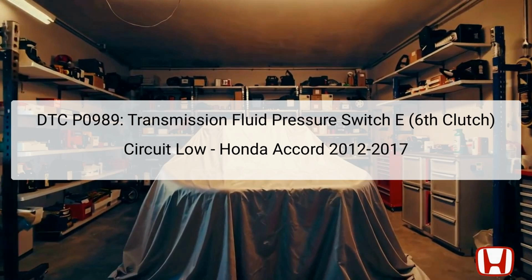Components involved include the transmission fluid pressure switch, located on the transmission and connected to the powertrain control module, or PCM. The role of the switch is to monitor fluid pressure, ensuring proper transmission operation. When this switch malfunctions, it can trigger a range of symptoms, affecting the vehicle's drivability and overall performance. It's critical to understand that this code is electrical in nature, indicating a wiring or connector issue rather than a mechanical failure within the transmission itself.